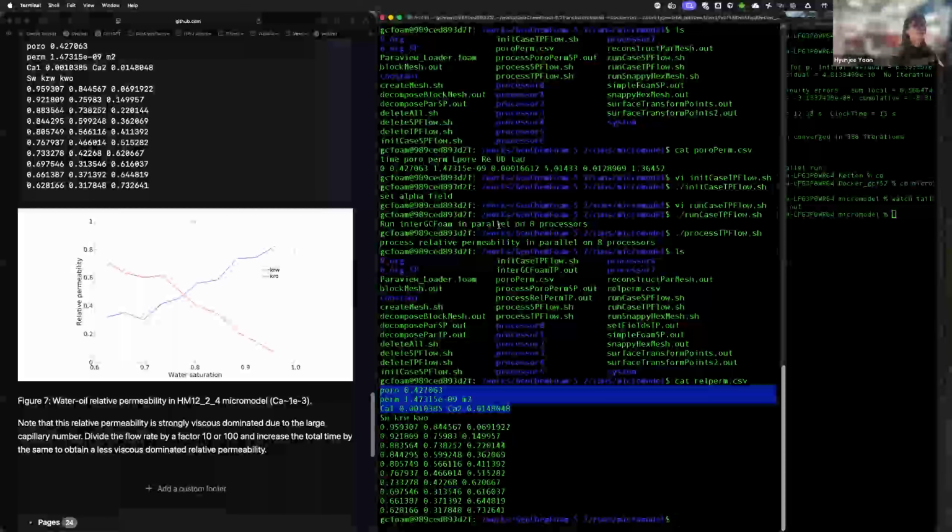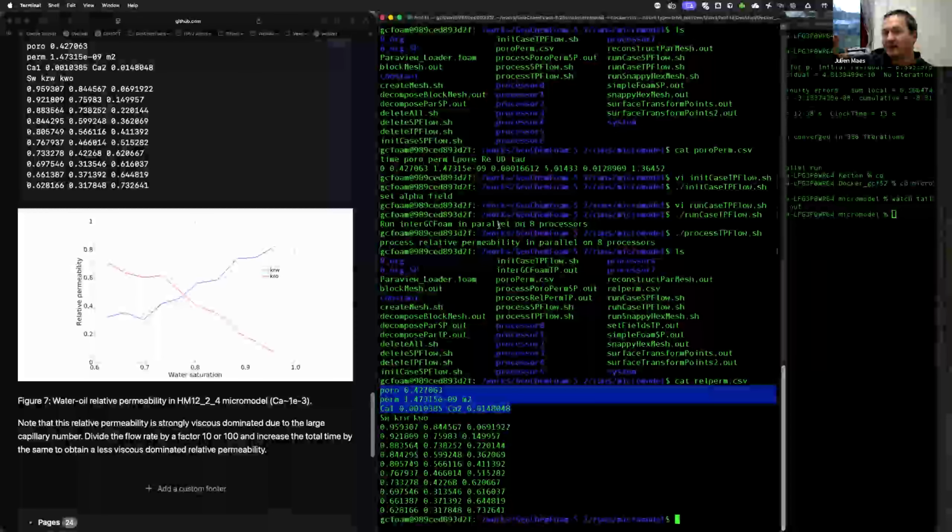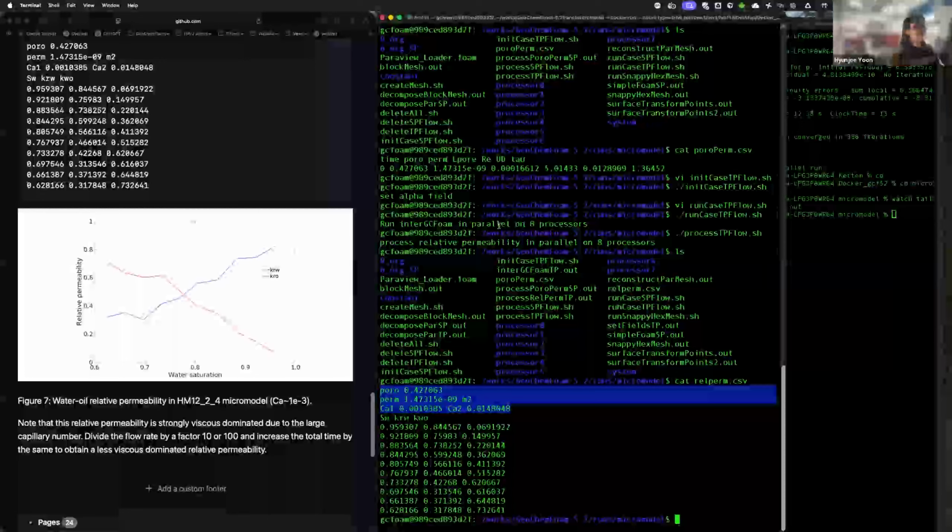Yeah. Well, we just went through Lattice-Boltzmann, and in Lattice-Boltzmann you can include a body force. But here you have a gradient of pressure in the actual simulation. If you're doing a body force, do you need to have a periodic system? Because everything that goes out must come back in, right? You need to have a periodic system. Right. A bit more complicated. So not in this case, we're injecting. It would be nice to be able to do body force, but again, it's going to make the system bigger, and we want it to be fast. Thank you.